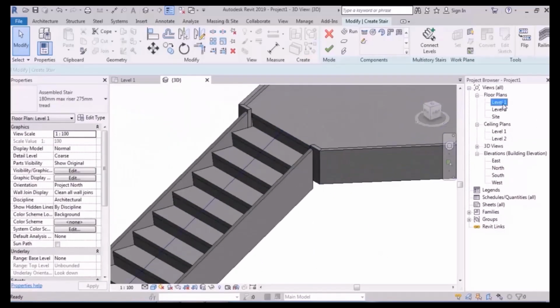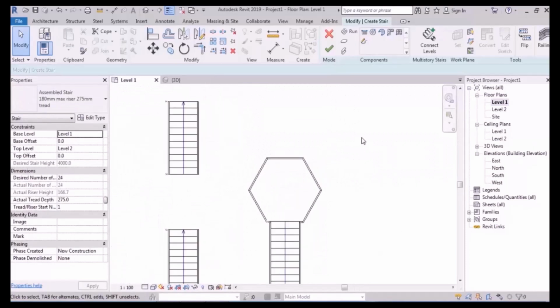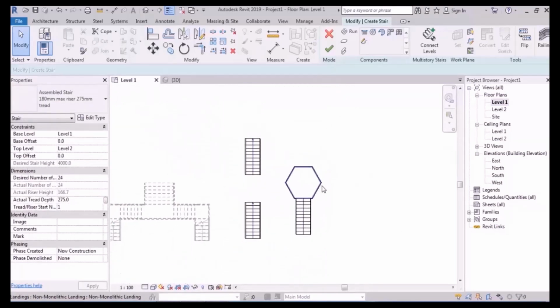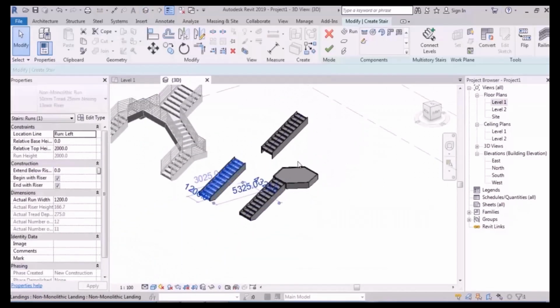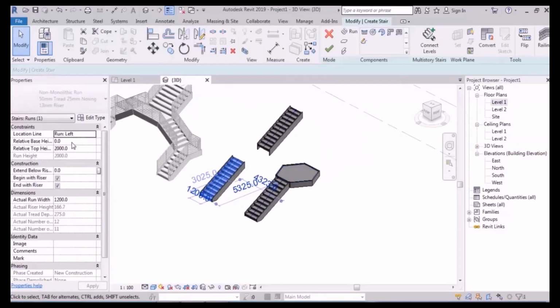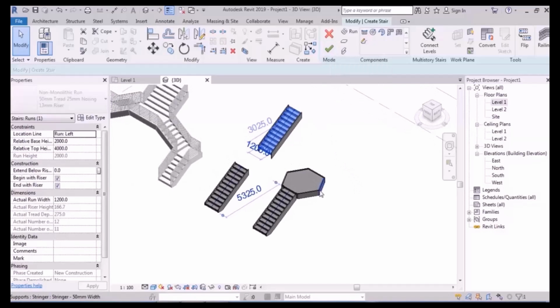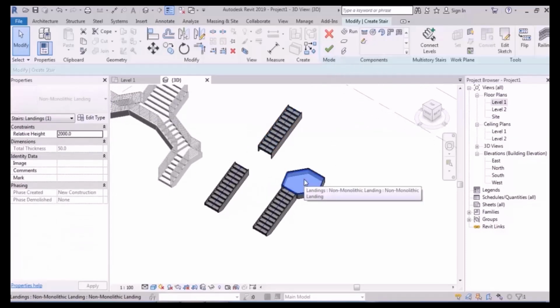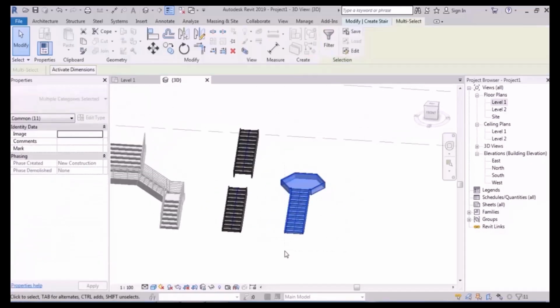Now they have a connection, but before that you need to check it. I told you some methods. You check it to make sure that there is connection. And now we are sure that everything is okay. Also remember that while you're drawing your stairs, they must never have the base offset. Well, of course, the stairs of the first ramp. The second ramp starts from a different height. But generally, the stairs must not have a base offset. So, if we draw the landing separated, which I said is useless, we need to adjust the height again.